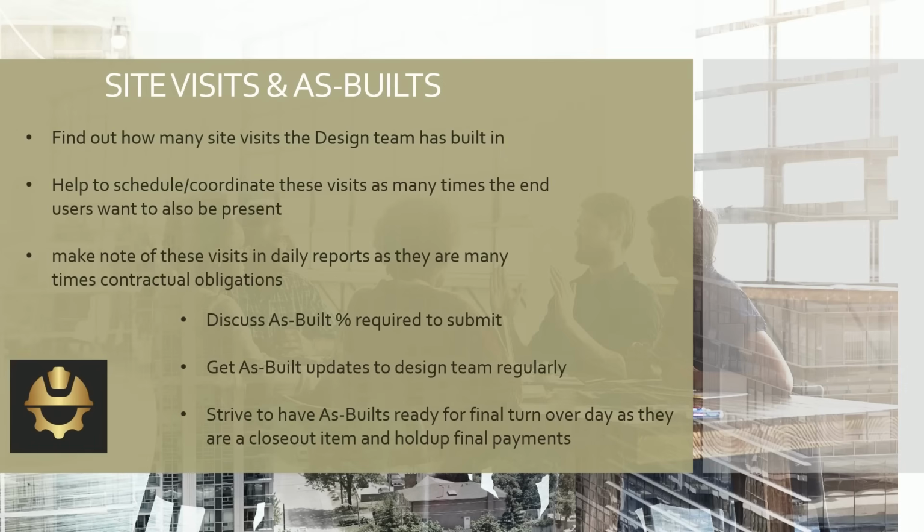Yep. You've got to make note of those visits in your daily reports because a lot of times they are contractual obligations, and then you can go back and say, yeah, we did this. We did a site visit at 25% or 45 or 60 or whatever it is, and we did it on this day. So it's important to make a note of that in your daily report and make note of who's present. If the end user didn't show up and chose not to come, it's important to make note of who was there on the walk, especially with staff turnover on your client's side. Then you get somebody who was more hands-on towards the end, and they say, well, we were never invited. No, you were invited, and your predecessor chose not to show up. But you need that information.